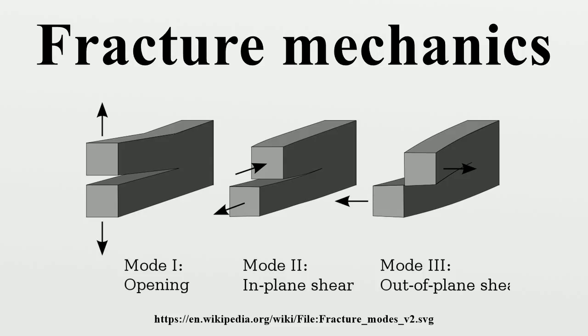It also demands that the assumed nonlinear elastic behavior of the material is a reasonable approximation in shape and magnitude to the real material's load response. The elastic plastic failure parameter is designated JIC and is conventionally converted to KIC using equation of the appendix to this article. Also note that the J integral approach reduces to the Griffith theory for linear elastic behavior.